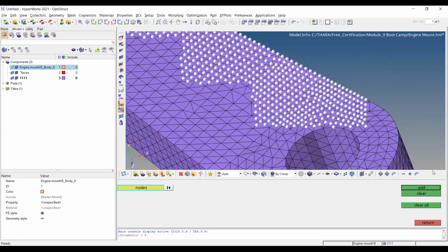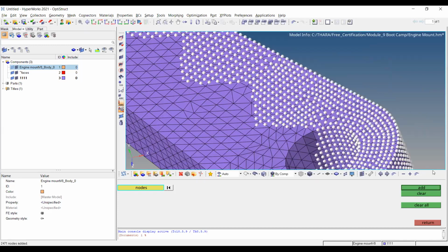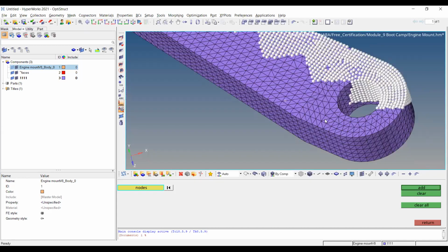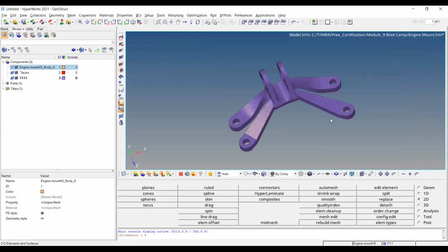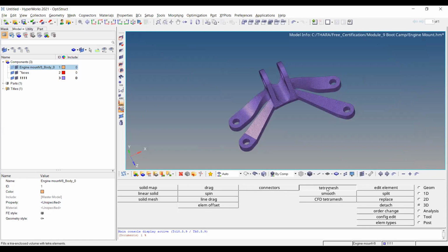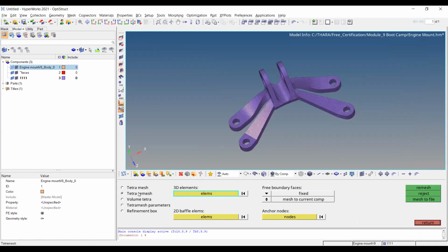So this is the basic concept of creating the tetra elements. These are the basic concepts to create any tetra elements. In this module, we have learned geometry correction for 3D. We have created the volume tetra, and we have created the standard tetra elements. For the standard tetra elements, we learned about floating and fixed trias, our remeshing option, and we have learned about the quality parameters.